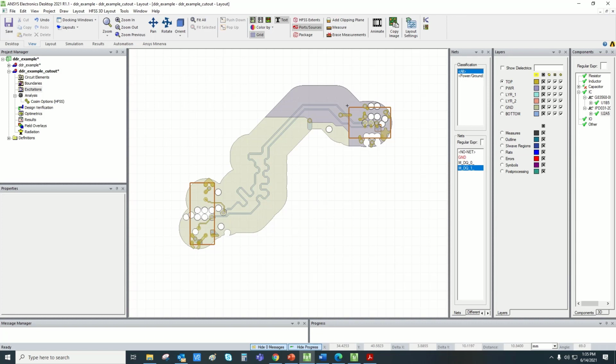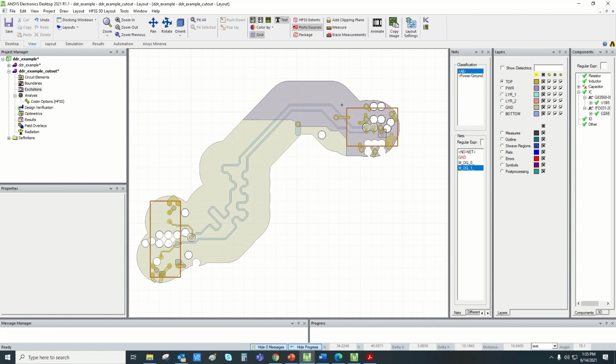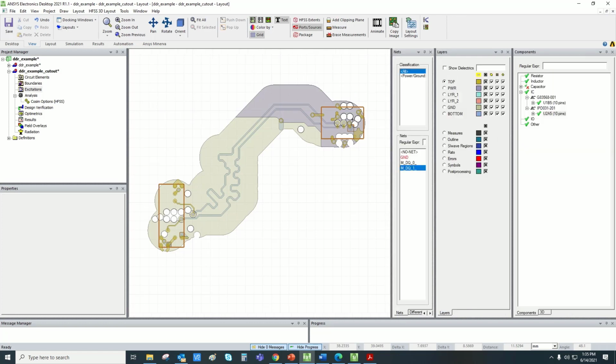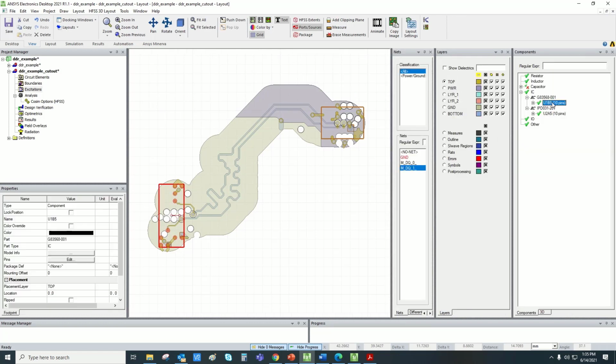So we need 3D HFSS regions over the IC component areas over here and here, and we would like to simulate the transmission line with a 2.5D solver. Okay, so in order to proceed, our first step would be defining ports at each end, right? To define ports for the IC components, let's define this side first.